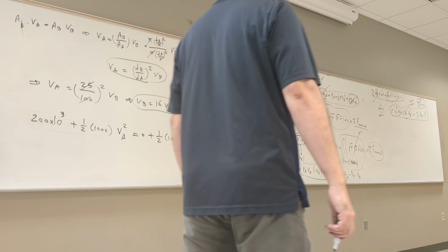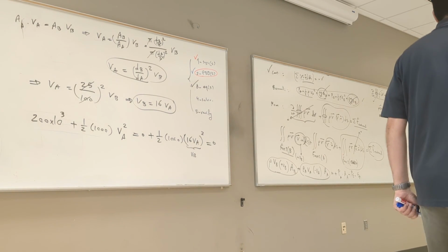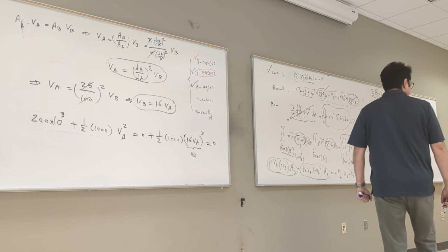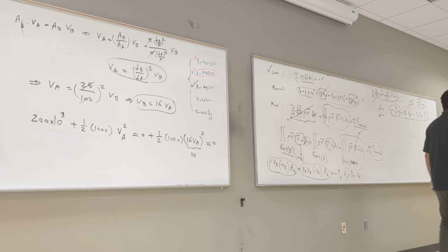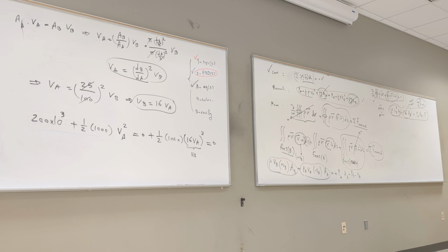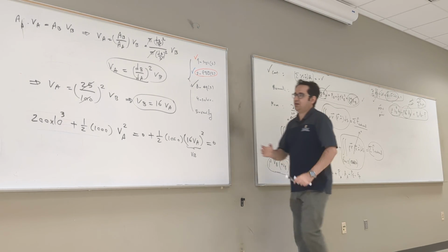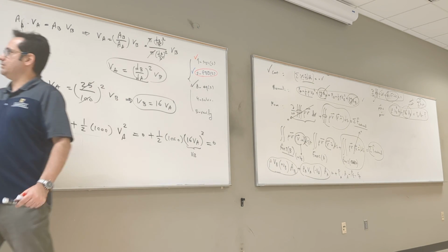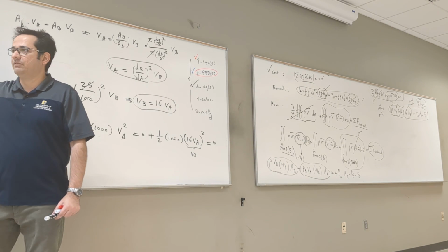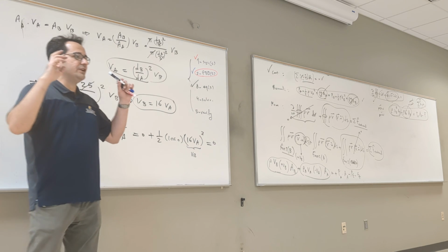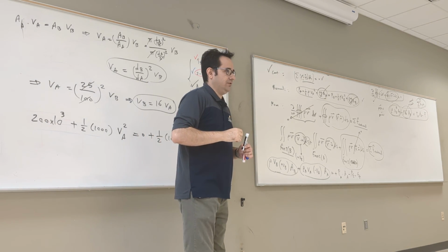What we said earlier is that Bernoulli's equation works with no friction. Well, as I mentioned, this equation is approximate. It's not exact. So we ignore the friction which comes through the surface of the pipe and distributes through the shear stress everywhere. We said this is frictionless flow when you write Bernoulli.